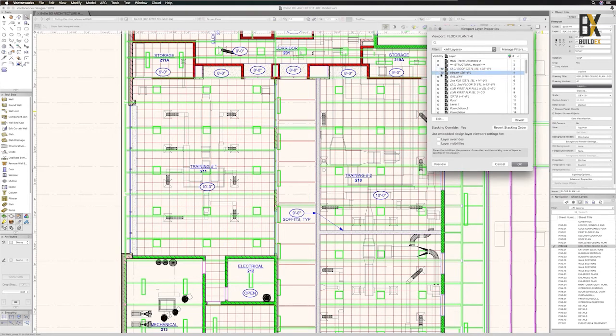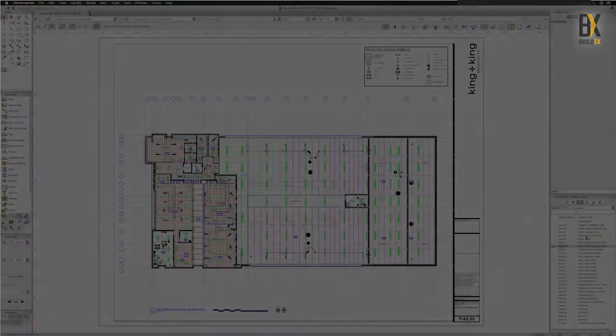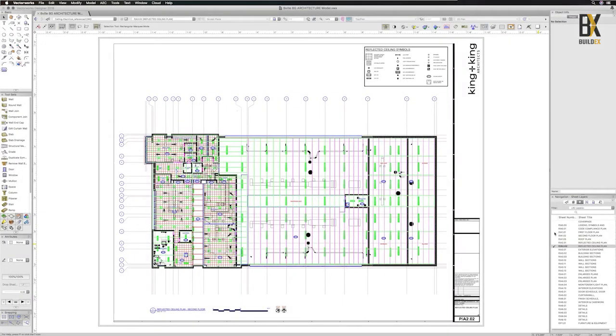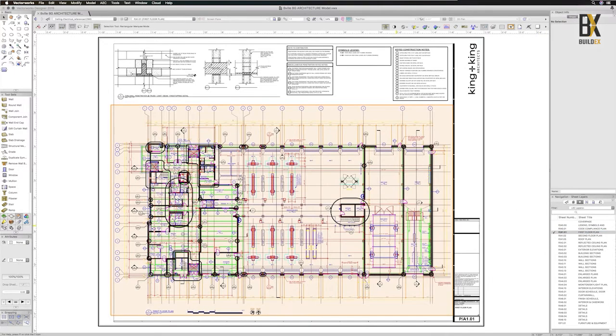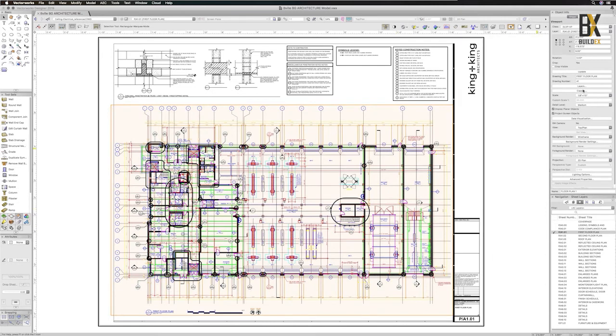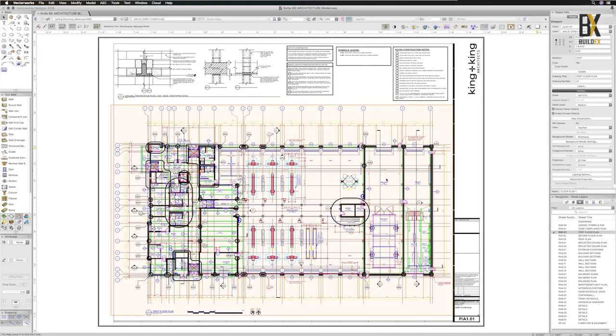Lastly, in this example, on the first floor, this is a bus garage, and it has a snow melt system. So there's a lot of piping in the concrete slab, and I want to ensure that all of that piping is coordinated and there's no conflict. So I can zoom into that area here, and you can see all of the zones for that radiant heat system that's in the floor slab.